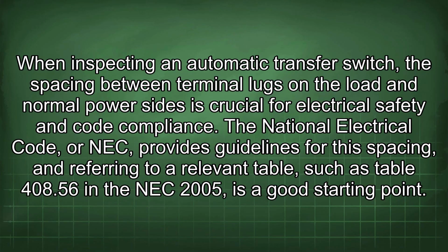When inspecting an automatic transfer switch, the spacing between terminal lugs on the load and normal power sides is crucial for electrical safety and code compliance. The National Electrical Code, or NEC, provides guidelines for this spacing, and referring to a relevant table such as Table 408.56 in the NEC 2005 is a good starting point.